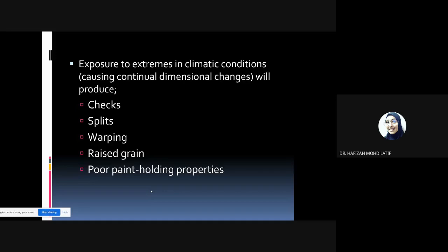And when you do the practical training, when you record the defects, you have to find the cause. For example, if the paint is peeled off, you have to understand what the causes are, what can make this paint peel off. So remember the 8 causes I've mentioned just now. You check one by one. Is it because of the weather? Is it because of the location of the building? Is it near the sea? The type of the building? Is it because of the quality of the paint? So you have to check all the 8 causes one by one for each of the defects.